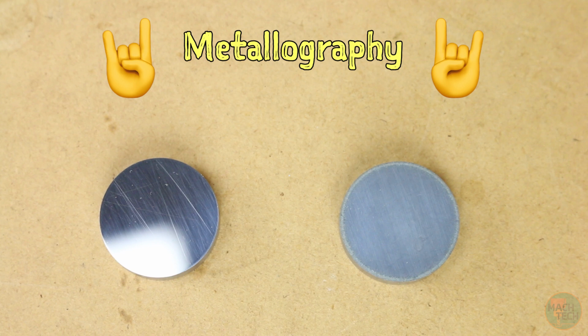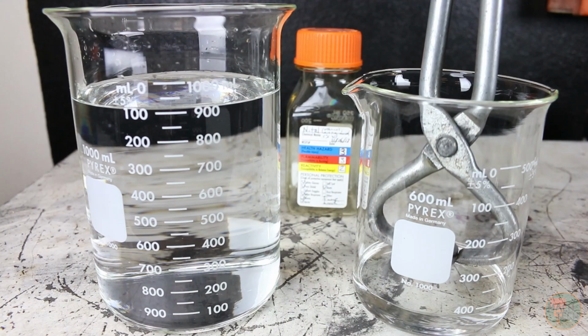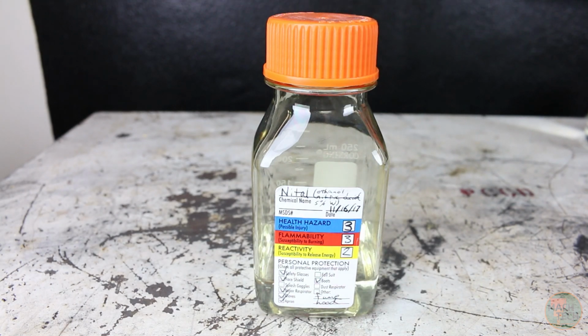Preparing a sample is a multi-stage process. You must first grind and polish the surface, and then you must etch it with some kind of reagent. For steel, it's typically nital, a nasty cocktail of 10% nitric acid in ethanol. This attacks the grain boundaries, highlighting them and other microstructures on the surface.